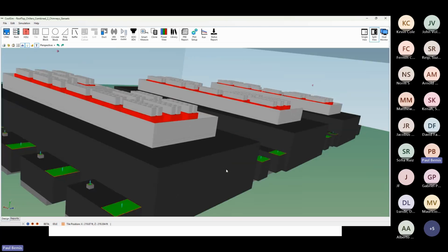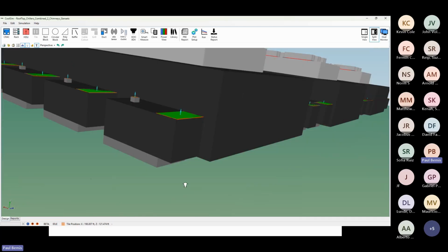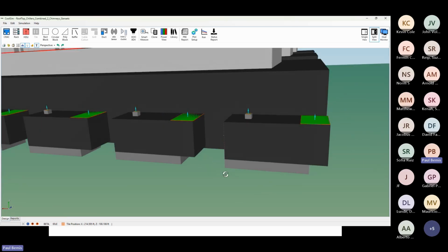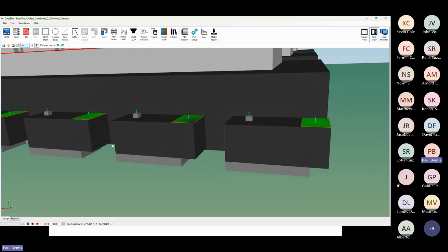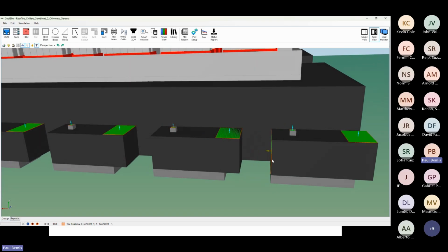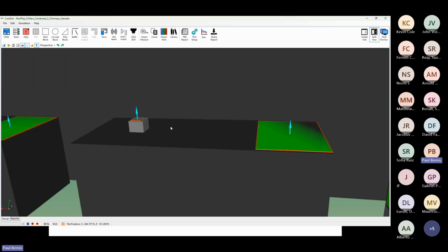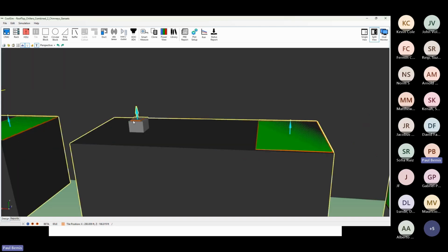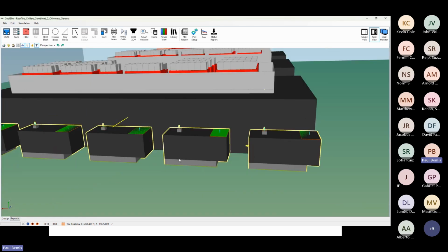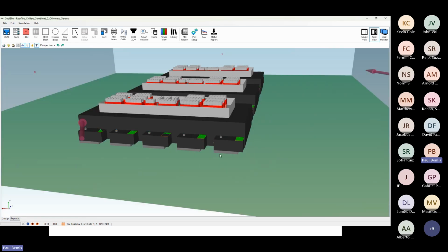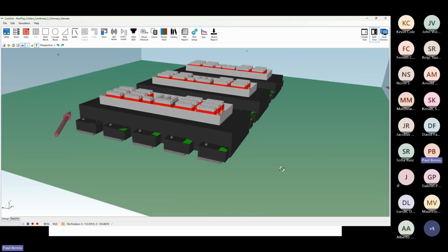So now the generators over here are modeled as fairly simple devices. We're not really concerned about what's in it. These are diesel generators in this case. We've got some inlets and outlets. So this is the heat exchanger cooling the device here. So you've got some air going through it. This is the stack where the exhaust comes out. These are quite simple. You simply set the boundary condition of these inlets and outlets and put them on a block. Once you create one of these things, you can clone it. So you just group that and say, I want 4 more of them with an offset of X or Y or Z.